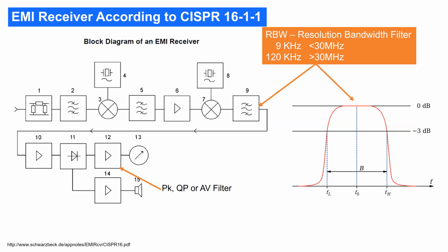If we want to reduce the, say, measured energy, we have to look a little bit at how the measurement systems, the EMI receivers, actually work. Now, typically it's a superhet mixer, a standard receiver, with a mixer first interface.